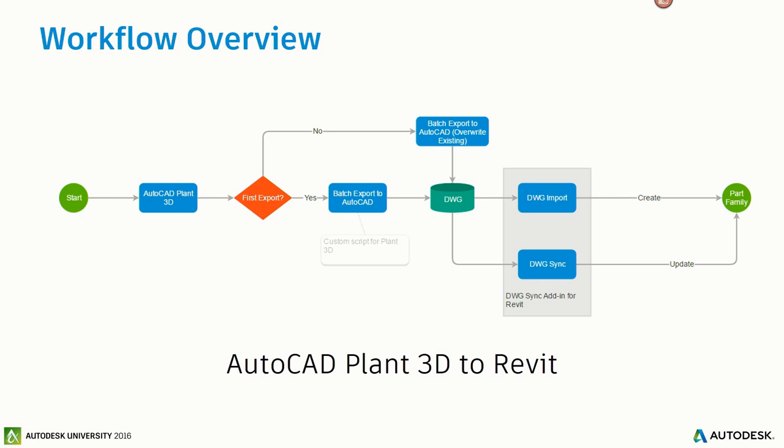Do you think there would be, you say that using DWG, you have to have a local DWG file to sync into Yeah. plans to make that like a recommendation file, not Vault or ASI? Well, you could have it stored anywhere on the network or on a Box folder, if you want to sync like that. With Vault, you would have to pull the file out of Vault and have it sitting there. But the fix on Friday, the build that they just sent out, was to fix a problem I found. I was trying to import a linked DWG file off a network drive, and it was just freaking out with some kind of error message. So they fixed that, so you should be able to link in.